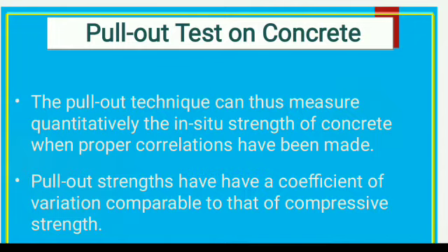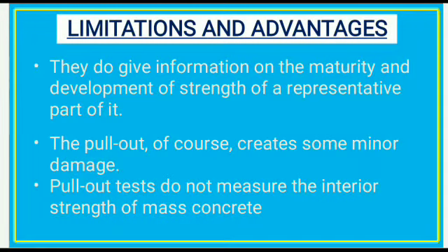Okay, we go to the limitations and advantages. They do give information on the maturity and development of strength of a representative part of it. The pull-out, of course, creates some minor damage. Pull-out tests do not measure the interior strength of mass concrete.